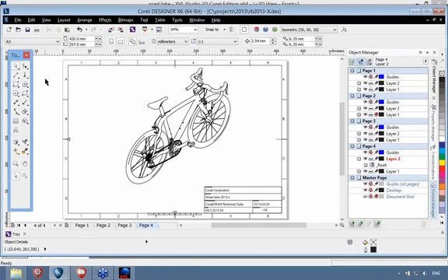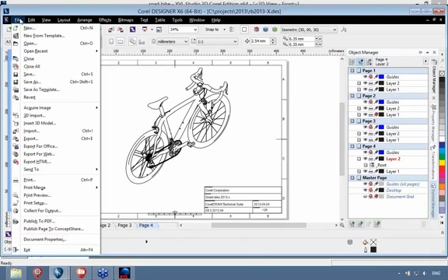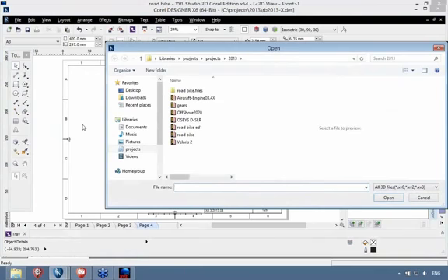But a really new thing with Corel Designer X6 I want to show you now is the option to insert 3D, not as an illustration, but as an interactive 3D in your illustration file in your Corel Designer page. So I use that same file. As you can see here, I can select the XVL file format. So that's a file that I had saved before. Could have been a 3D Studio or a DWG, or maybe an advanced 3D CAD file format that I used with the add-on of the 3D XVL Studio application.